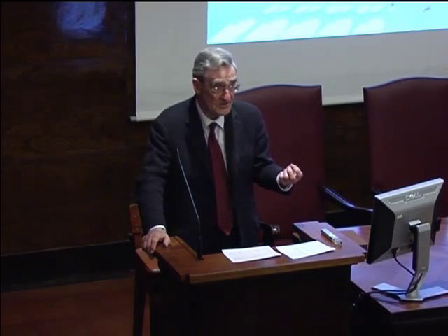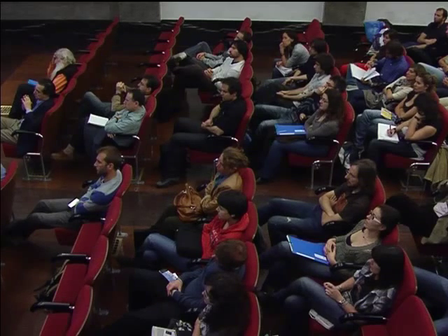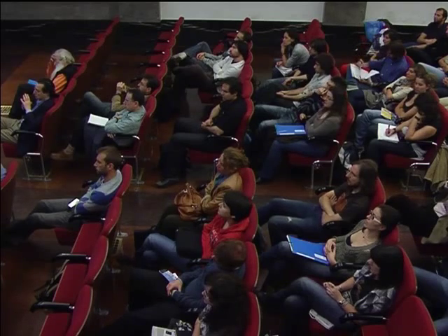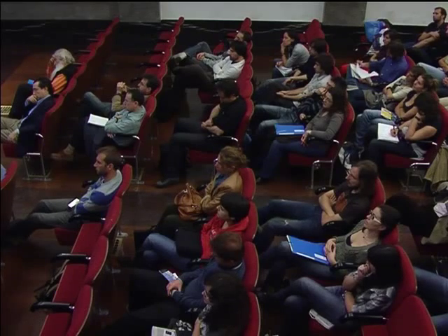What then happens if, for example, the surface is uneven and is unable to provide the support required by the membrane equations? Then one must look at the assumptions one has been making. Strictly speaking, the solution is no longer valid. In practice, what happens, of course, is that the shell will deform slightly, that is, the geometry will change, and we've assumed a constant geometry in the membrane equations. The elasticity of the dome will allow certain displacements to occur, and we have ignored displacements.